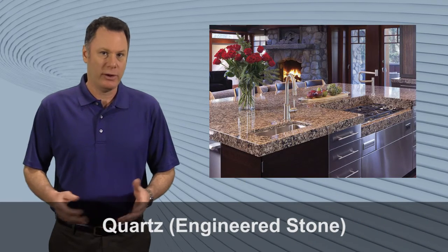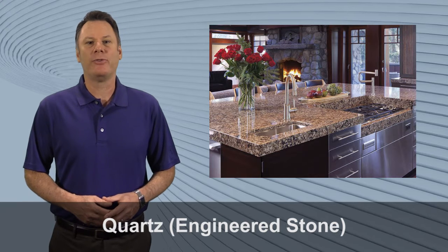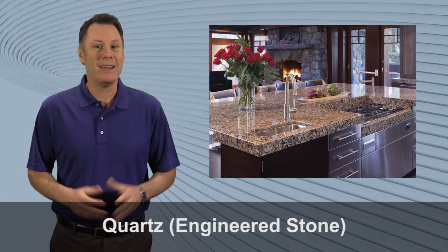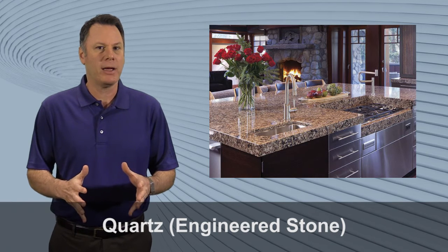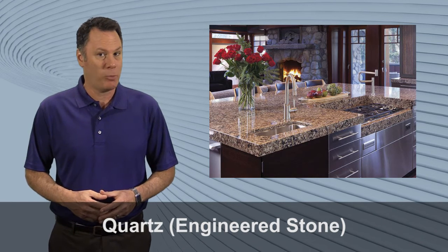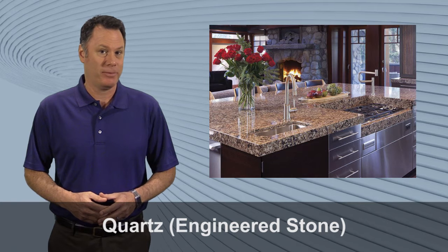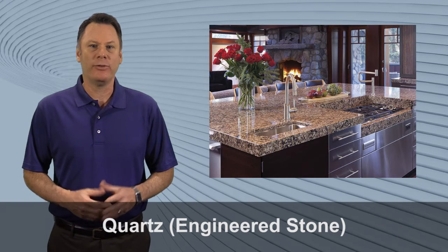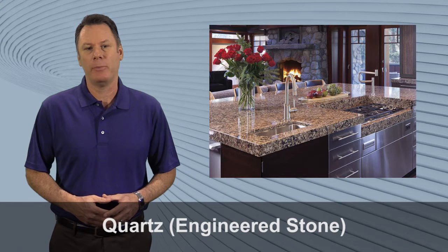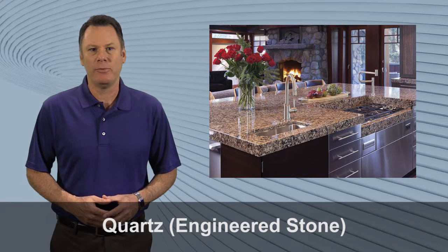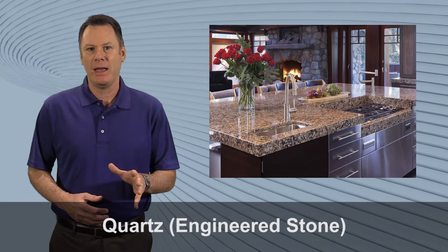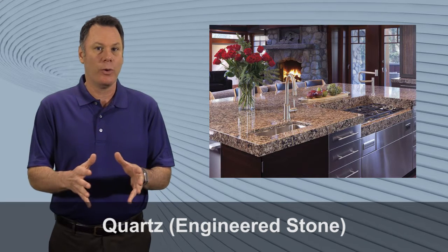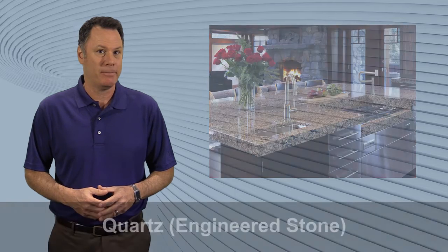Quartz, engineered stone. Engineered stone is a surfacing material that is well suited for applications where a hygienic surface is required because it is scratch resistant, non-porous, and NSF approved. However, because quartz engineered stone is installed in a similar way to natural stone slabs, engineered stone installations may have slightly open seams that can be susceptible to moisture penetration and bacterial growth if not properly maintained.